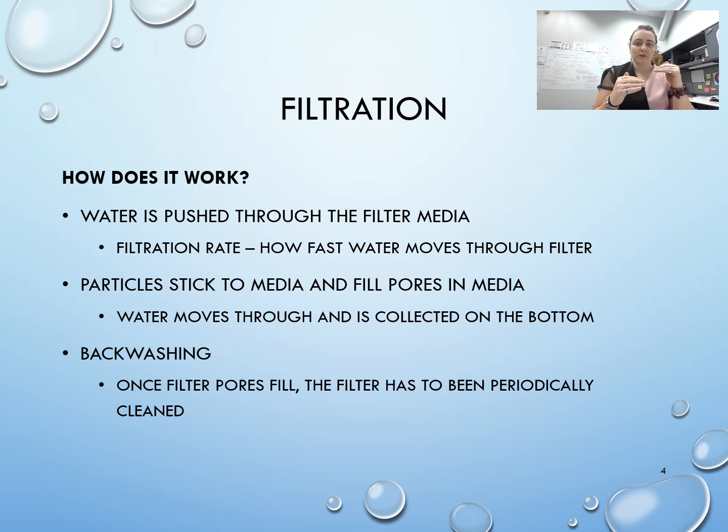So how fast that water moves through is what we call our filtration rate. So we push water through a media which has pore spaces in between, and anything that is nasty in the water gets collected on those surfaces, and then the water is collected out at the bottom of the filter.